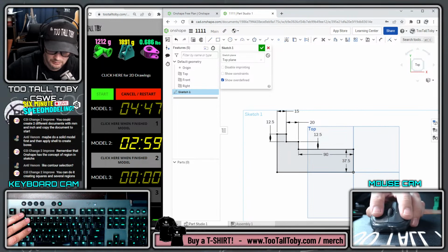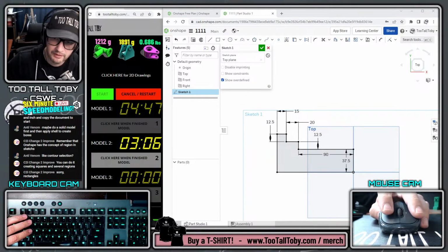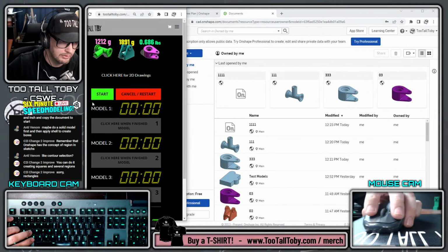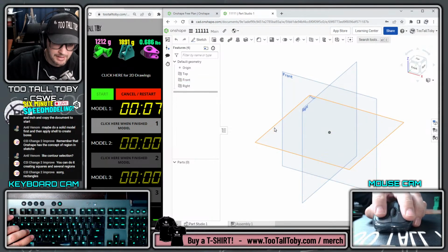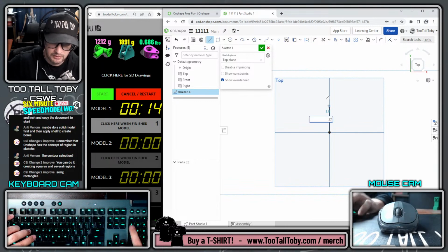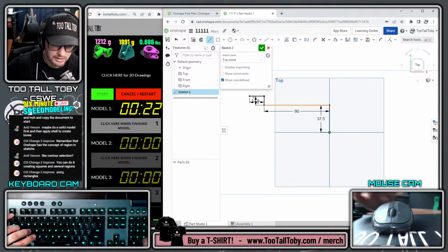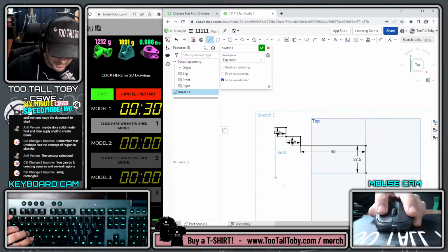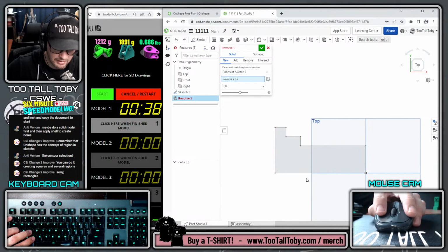I'm going to screen capture this and drop it onto my second monitor to help. A little cheat sheet here, this is totally legit when you're doing the Too Tall Toby leaderboard challenge. So, all right, let's restart this thing. All right, here we go. So we go top plane, begin a sketch, get normal to. We go line 37.5, come across 90, come up 12.5, come across 20, come up 12.5, come across 15, come down, close this thing off, and then turn that into a revolve, and I'm going to use this as a revolve axis.